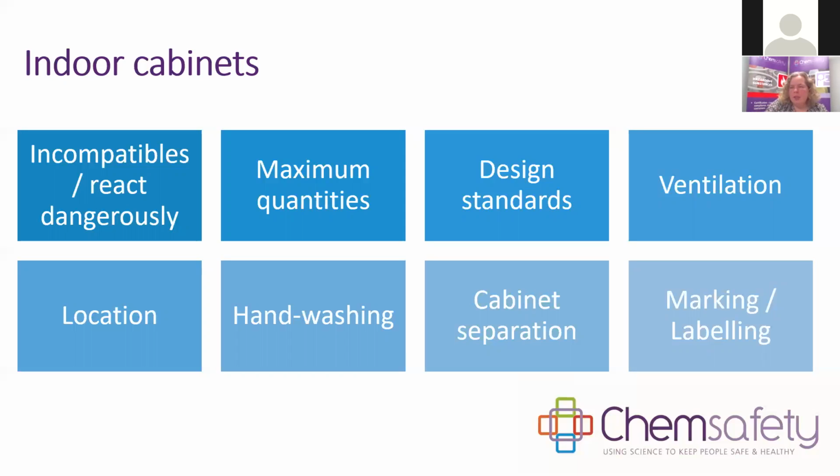If you are ventilating your cabinets, make sure that they're discharging in a safe location and that the location's not impeding safe exit, that you've got somewhere to wash your hands, and that your cabinets are separated from each other, and they should also be marked and labelled. So indoor storage cabinets is a way for dealing with smaller quantities, but be aware there are some quantity limits as to what can actually be in a cabinet or a cluster of cabinets.